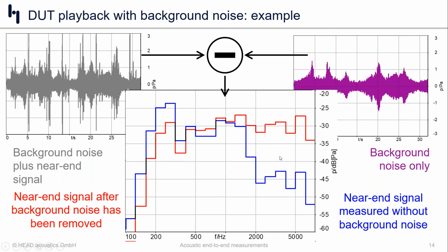Now, without listening to the files and doing more analysis, it's hard to say exactly what the device is doing, but it could be a fairly simple compensation here in the higher frequencies to improve intelligibility. So maybe it's amplifying the speech content up around 3-4K where human ears are very sensitive. That's one guess. It could also just be non-speech-like content. Either way, it maybe sounds tinny. Certainly we've lost some bass response. So the device is clearly changing behavior, and this is definitely the way for us to go about doing it.